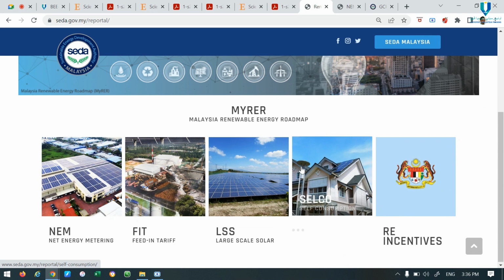First, you use your own energy generated from the PV system. If not enough, it will trigger to the TNB, then you start to use from the TNB. So the significance is to reduce the electricity bill, of course, because you use your system first. If not enough, then you pull from the TNB. I believe there's an ATS system, automatic transfer switch, or maybe a smart switch that can change the power supply from your PV to the TNB without any interruption. Maybe I don't know the recent technology. I'm not focusing on Selco yet.